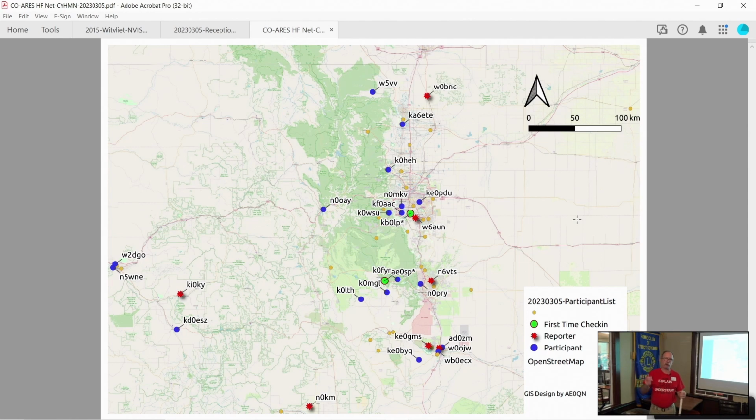They'll be a narrower band. The ham sticks, as I understand it, have a tunable tip on the end. So without retuning, you only have a portion of the band, but you could use them horizontally. Again, if you can get them 15 feet, that'd be good, and that shouldn't be hard at all to get a couple ham sticks up at 15 feet. Now, would you try to angle them or keep them horizontal? Keep them horizontal.